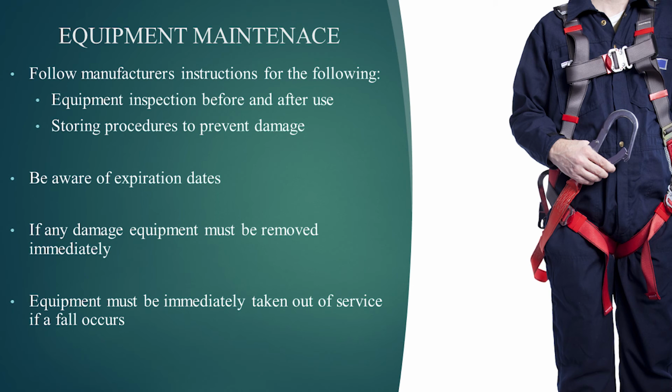If a fall incident occurs, immediately notify the TUSD Director of Operations and the immediate supervisor of the employee involved in the incident. The equipment that was being used during the incident must be taken out of service immediately until it is inspected by a competent individual who can determine if that equipment is safe for use again.